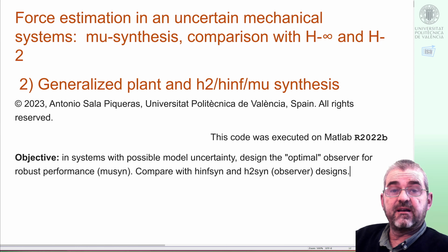I'm Anthony Sala, and in this video we will continue with the case study about designing a force estimator with modeling errors. In a first video we discussed the LFT uncertainty modeling phase. In this video we will build the generalized plant and will carry out H2, H-infinity and mu-synthesis optimization. Performance comparison in time and frequency domains will be left for a forthcoming video for brevity.